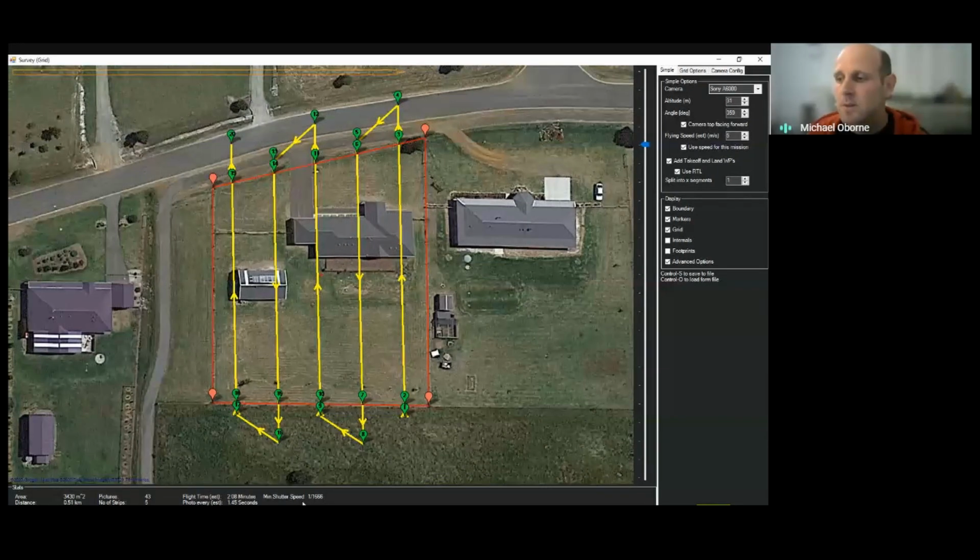This field is based on your flying speed and will determine how much motion blur the photo will have. If you use a shutter speed faster than the number quoted here, that will decrease the chance of motion blur. Anything below this number and you start into pixel motion blur, which of course means a worse final result in the orthophoto or the digital elevation model.